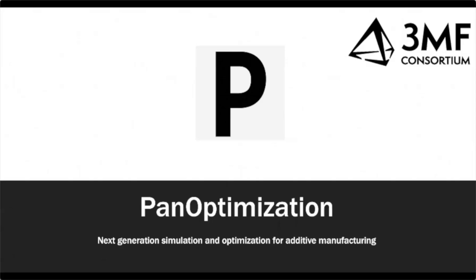So, yeah, the meshing could be used for any other application, either FEA or CFD. The thing to note is that the mesh is not uniform voxel, so there's octree adaptivity, and there appear to be what are called hanging nodes. They're not really hanging, they're constraints associated with those nodes. So whatever simulation software it's going to be used with has to have an efficient way of handling constraint equations, because in this kind of problem, usually about a third or maybe a quarter of the degrees of freedom in the model are constrained. So it has to be a very efficient approach. In our approach, we use condensation. If you have something less efficient, like a Lagrange multiplier approach, it's not going to work. So that's the main constraint.